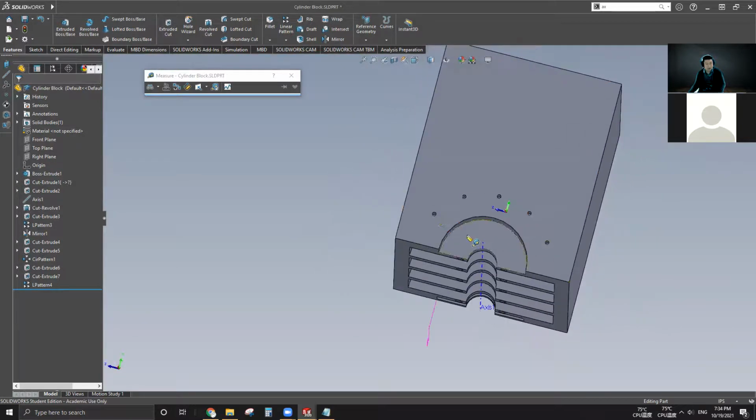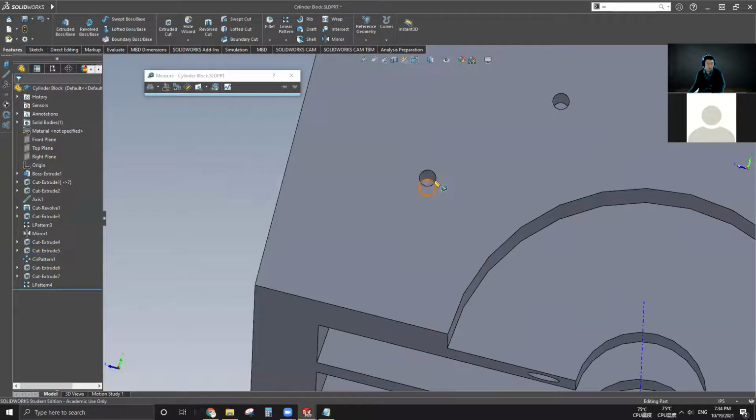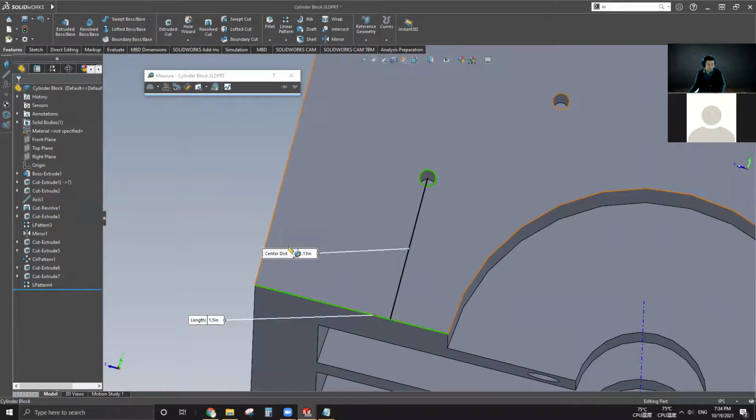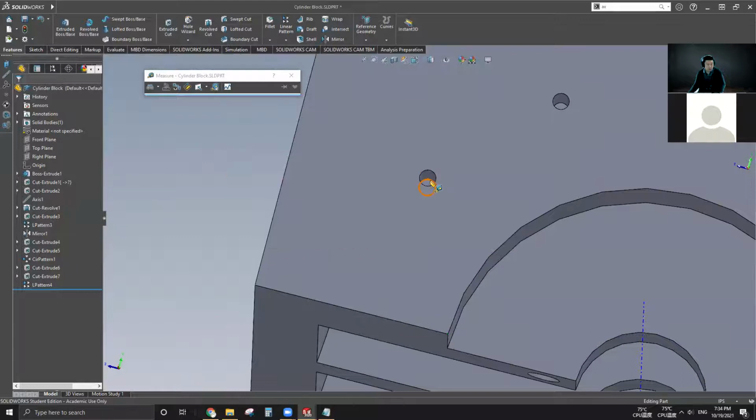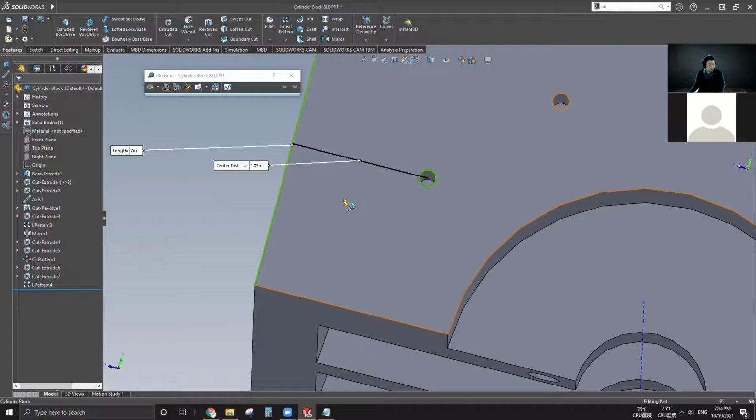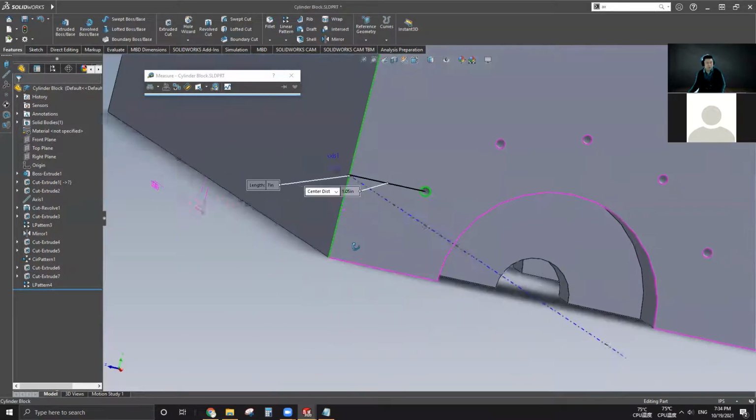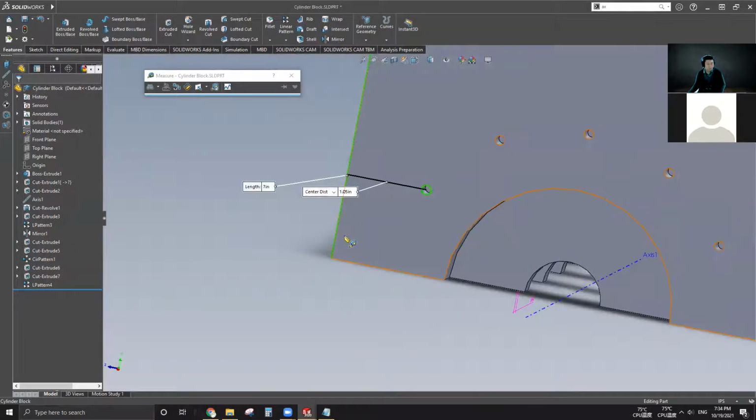It's a little bit hard to tell if they are meant to be symmetrical with 10, but from this distance, it doesn't really look like it. So we have to set up a hole right here and then do a circular pattern so it can have 5. So 1 and 1/8 from the bottom, 1.05 from the side,